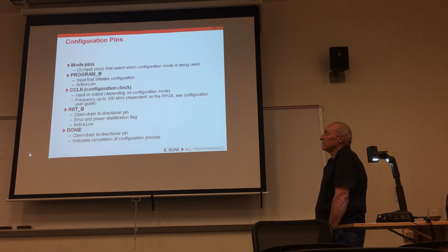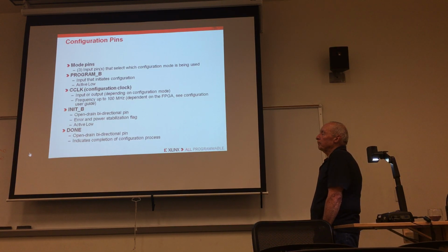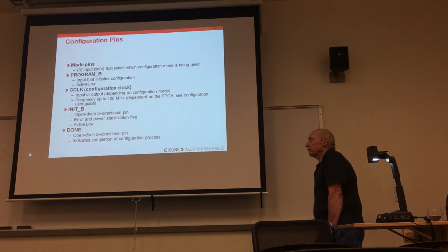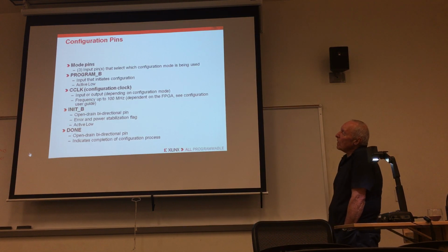The done pin indicates the completion of the configuration process. It's bidirectional, so the user can delay the startup sequence. After configuring the FPGA, the starting of the FPGA is often controlled by the user to control the releasing of the entire FPGA system to operate. On a side note, in case you don't know, BitGen is the bitstream generation utility included with the ISE software. It is used to create a bit stream from the implemented design and is used for configuring the device.